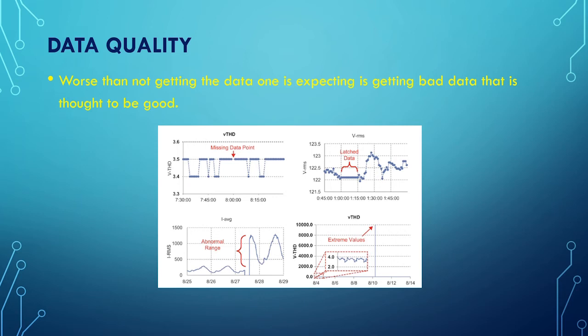This can also show up as a false positive for latching if a measured value is using a fraction of bits resolution from the analog to digital converter. The next one is the abnormal range. This is when a trend goes outside the normal range of operation.